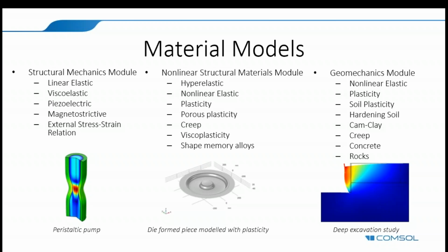In terms of nonlinear material effects, you can, of course, model elastoplasticity to allow the material to yield where it transitions from being elastic to elastoplastic. This allows you to model the post-yield behavior where the material is permanently deformed and doesn't return to its original shape. This would be relevant if you were looking at, for example, a metal forming process where you are modeling a purely mechanical process and forming the shape of the part through the mechanism of elastoplasticity, by punching it out.